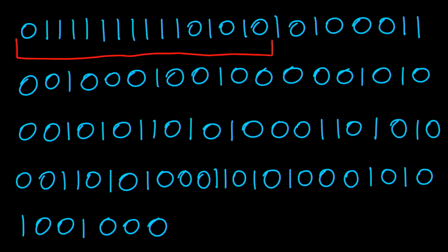So what we end up seeing is a common prefix, like a training sequence, just to help the reader realize that there's a card here and you should pay attention to the following data. That's always 7FEA, I think it is, in hex. And then we have the last eight bits, which turn out to be something.